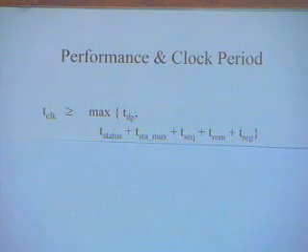In the next class when we design the sequencer, we will find that there could also be loops within the sequencer. What we call loops here is, as far as the clock period computation is concerned, we have to consider all paths which go from one register to another register. A register output to register input. It could also be the same register input, that is also a loop. So anything which goes from a register output to register input is a path, and the clock period has to be the maximum of all such paths, because once you generate a register output, it should be stable at the register input for latching it in the next clock in a single clock design.